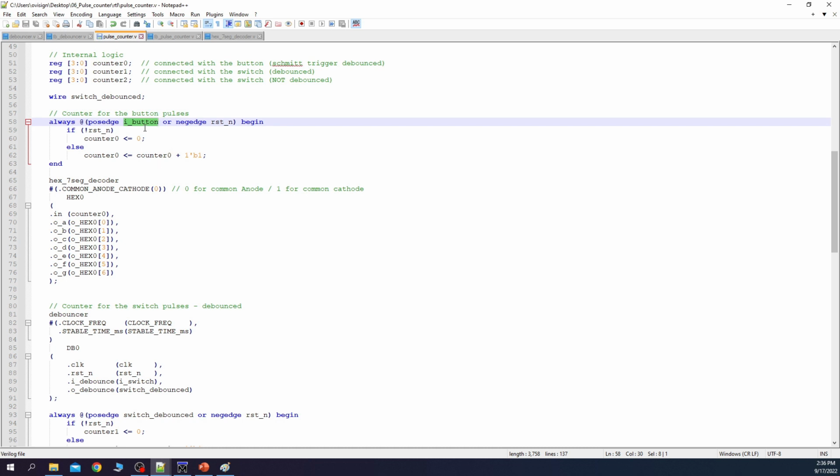In general, you should use only posedge clock. An I button should be inserted in the logic inside the always procedure. But I use this to reduce the number of logic elements inside the circuit and also to prove what happens when a noisy input is inserted inside a digital circuit. Whenever you press the button debounced with the Schmitt trigger, this will increment the counter by 1.